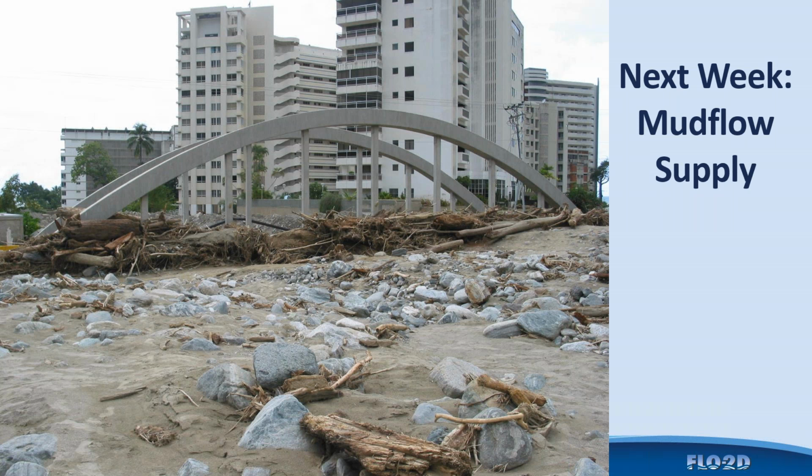And I've started programming that, and I have it completely conceptually outlined how to do it. We would track the sediment volumes in both models and have vertical exchange in both directions for the mud flow to the conventional sediment transport, and from the conventional sediment transport depositing back to the mud flow to keep it moving. So that will represent a better opportunity to model those kind of tailings dam conditions that have the water sitting on top or having an inflow hydrograph to a tailings dam.